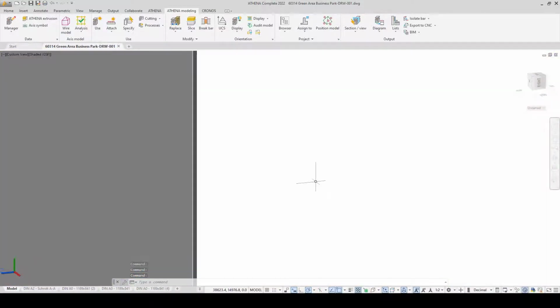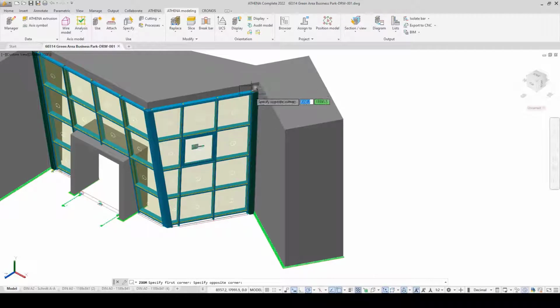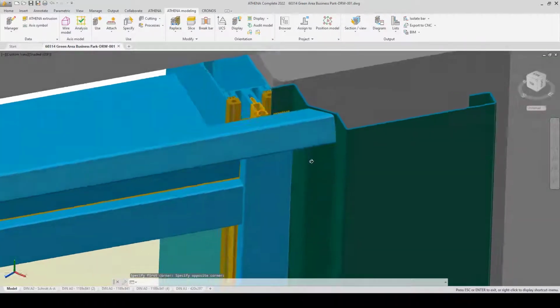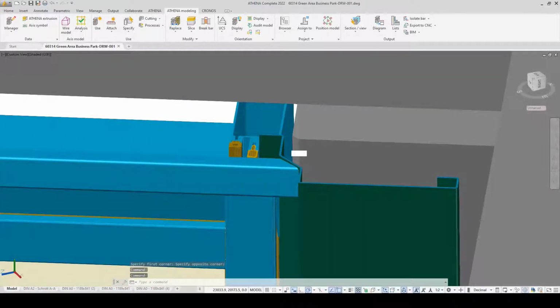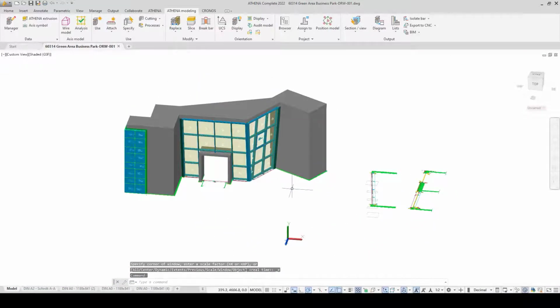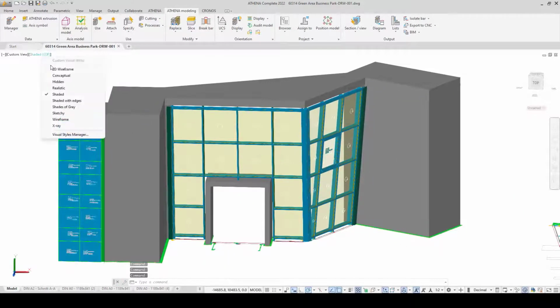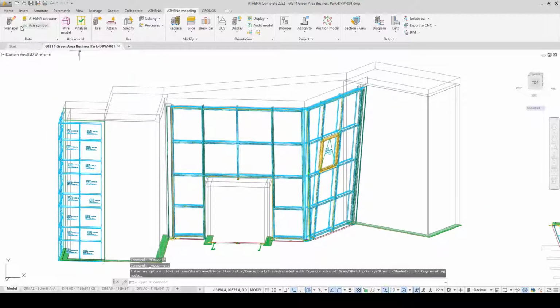In AutoCAD 2022, this is activated with the system variable 3D Tech Preview. In 2023, this mode is available by default under shaded and shaded with edges. Just look how fast I can rotate and turn this 3D model smoothly. The performance is raised considerably here.